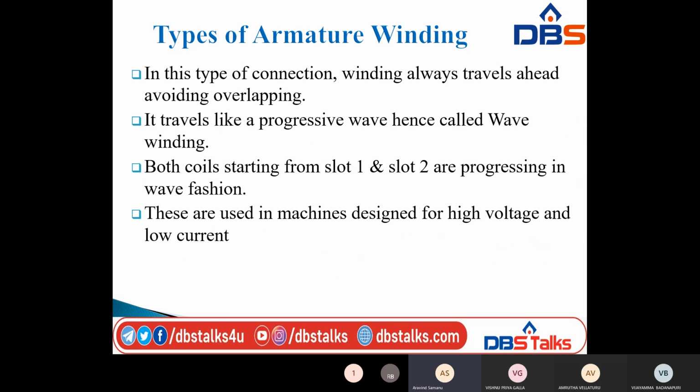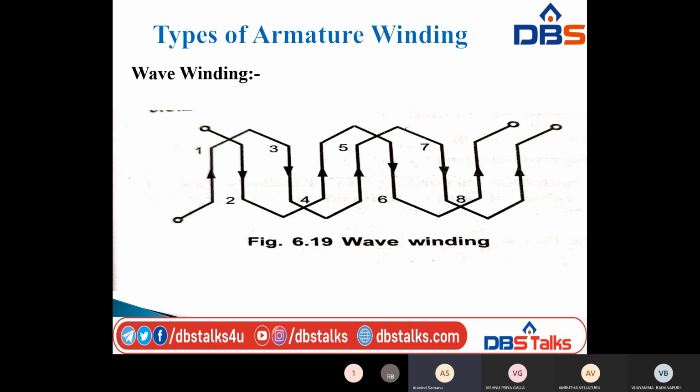And next, both coils starting from slot 1 and slot 2 are progressing in wave fashion. Here this is one coil, it starts from slots 1 and 2, another one is 3 and 4, the next one is 5 and 6, next one is 7 and 8. So in this way it travels.